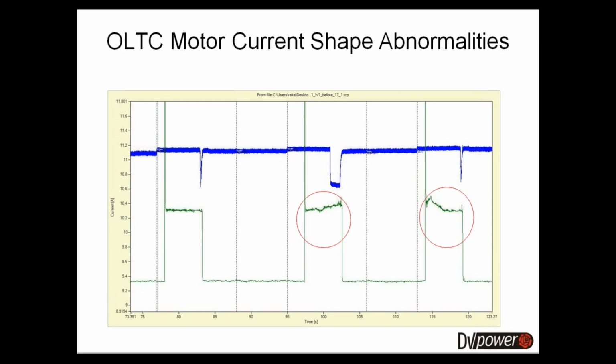Because on the second one, as the tap changer operates and moves the spring towards the point where it actually moves the positions, you can see that this force is not applied equally, but that it increases as the tap changer operates. And this increase in force is visible as the increase of tap changer motor current recorded by the instruments.